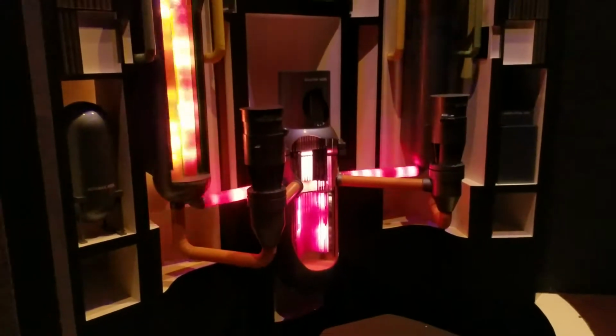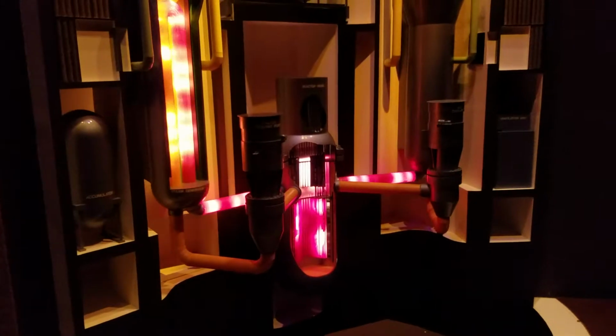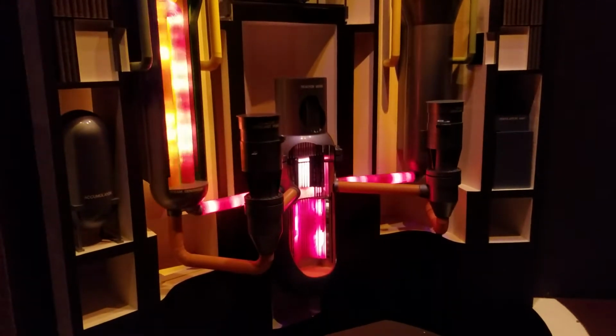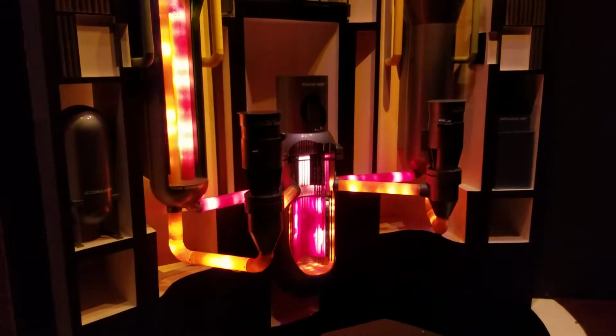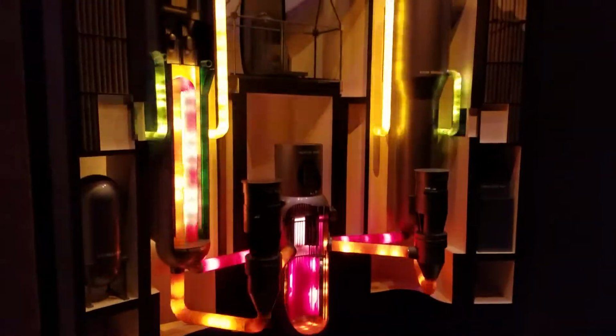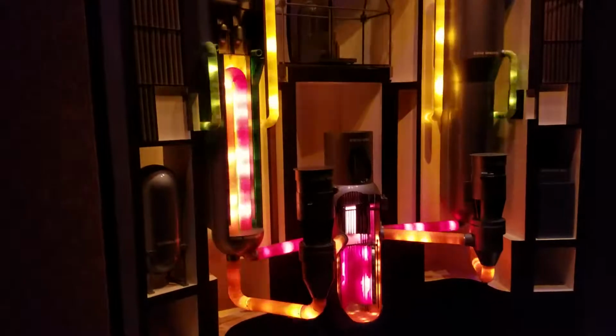The heated water in this primary loop flows into heat exchangers called steam generators, where the heat is absorbed by the water, which is circulated through a second, separate loop. That water then turns to steam. The two loops are entirely separate. Only heat, no water or radioactivity, passes from the primary loop to the secondary. Now, let's move over to the control room.